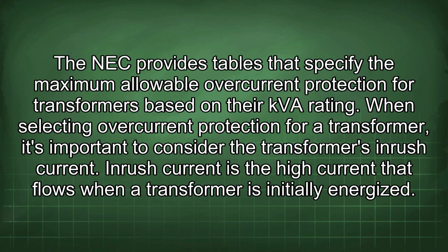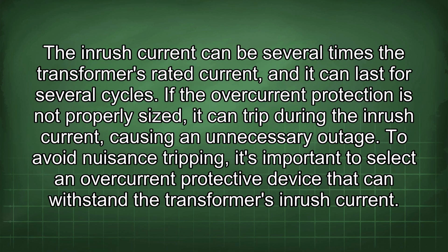When selecting overcurrent protection for a transformer, it's important to consider the transformer's inrush current. Inrush current is the high current that flows when a transformer is initially energized. The inrush current can be several times the transformer's rated current, and it can last for several cycles.